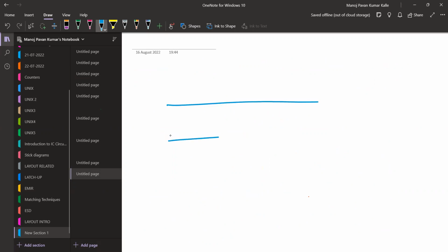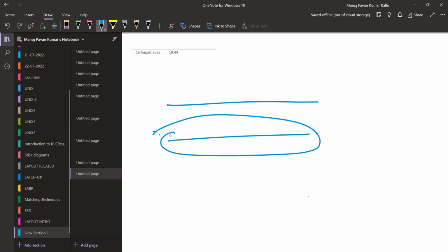There are two signals. Among these two signals, let's say this one is some critical signal, and the guy who drew the layout for this schematic didn't care about these two signals. He just routed these two signals, and after completing the post layout simulations, the designer sees some coupling capacitance between these two nets.